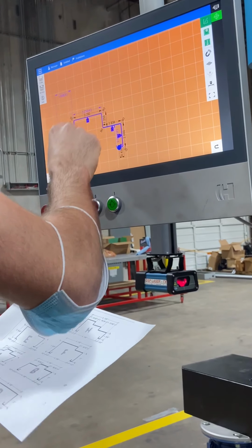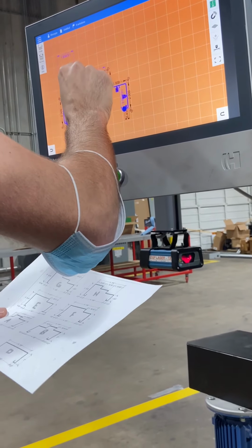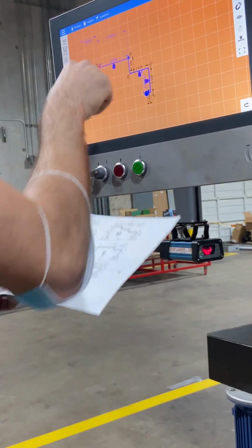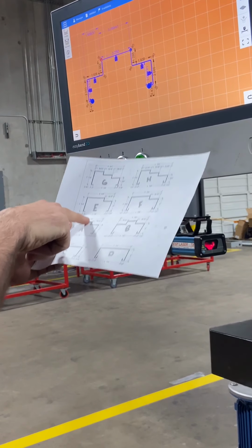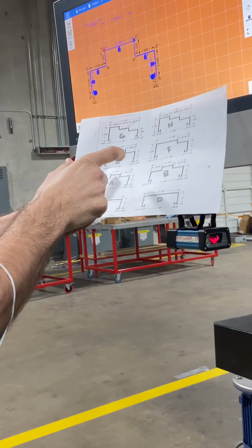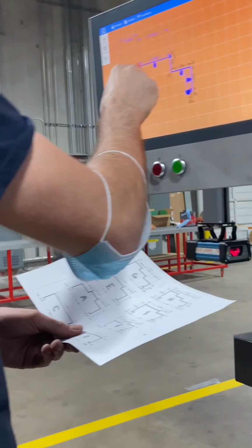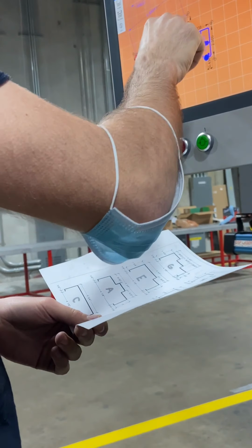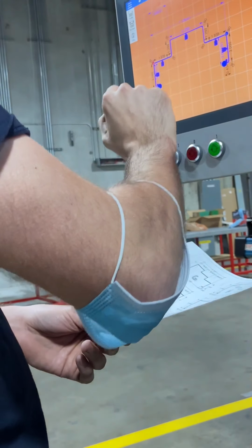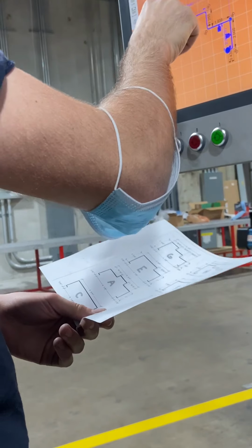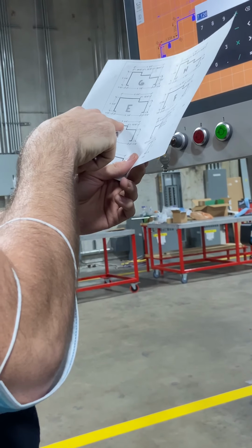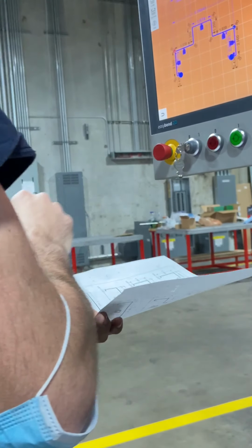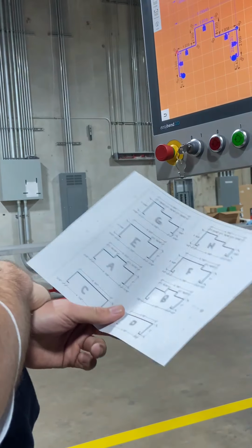And then this guy, I don't necessarily know what it is, because it doesn't show, but it does give me the overall width. So what I'm gonna do is change this value according to what I measure right here. So now this says 7.126, but I actually need that to be 5 3/4. So I'm gonna go 5.75, and boop, there's my part.